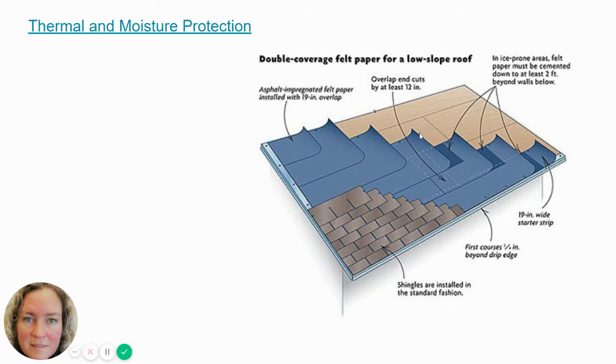Okay. For a roof system, you have the layer of plywood sheathing down here, and then we have what's called felt paper, and it's laid in overlapping formats like this, so that you can see that we're overlapping both widthwise and lengthwise, so that you're creating pretty strong barriers between moisture and any other kind of things, because these sheets are overlapping each other and adhered.